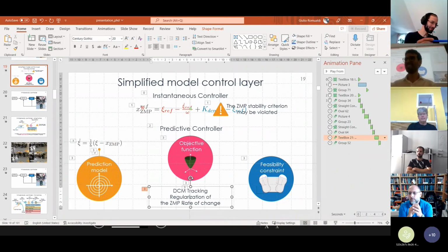That was question one. Question two was basically the one that Marco already covered and Jerry also had in mind, like this ground truth versus these flexibility estimators. I'll ask a somewhat similar question. You have the contact model and that's fed into the whole body controller. I'm not sure if you examined that, but how robust is your whole body controller to an imperfect model, maybe the same model but with different parameters?